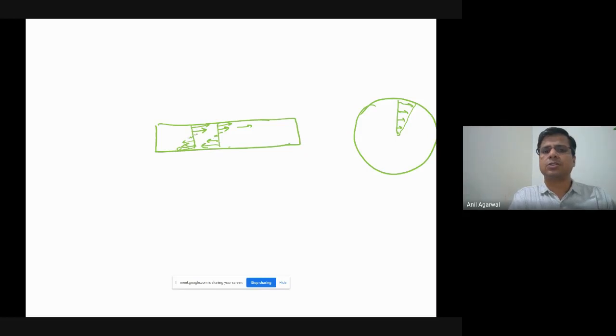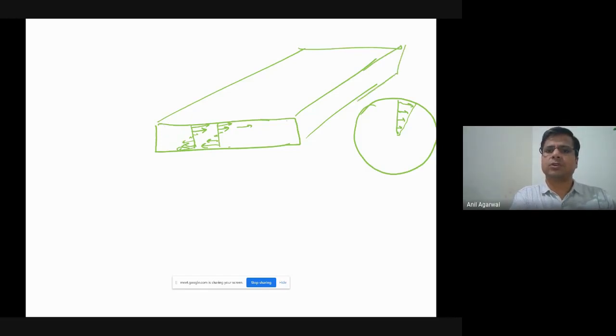As a consequence of these shear stresses, you will end up getting a twisting in the plate. So the plate was going this way. If, let's say, that end is fixed, you will end up getting some kind of a twisting. So if this is the neutral axis, the twisting will make it go up this way and this way. Okay.